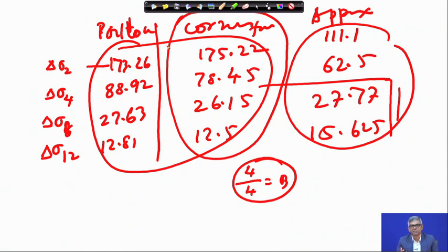Sometimes people use charts, though I have not shown that chart. If you see any book, you will see a number of charts given with m versus n and the influence factor Iq, which can also be used. Otherwise, in exam calculation most of the time we do not expect the corner formula, we generally use either the approximate or point load formula. If you want to get an accurate value, obviously the corner formula is preferred, but you have to do a lot of calculation.